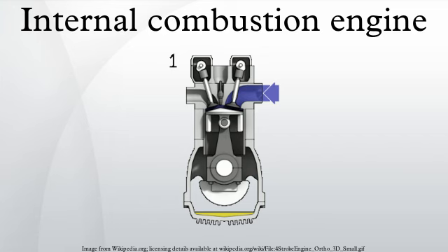2. Compression stroke. In this stroke, both valves are closed and the piston starts its movement to the minimum volume position and compresses the fuel mixture. During the compression process, pressure, temperature and the density of the fuel mixture increase. 3. Power stroke. When the piston reaches a point just before top dead center, the spark plug ignites the fuel mixture. The point at which the fuel ignites varies by engine. Typically it is about 10 degrees before top dead center. This expansion of gases caused by ignition of the fuel produces the power that is transmitted to the crankshaft mechanism.